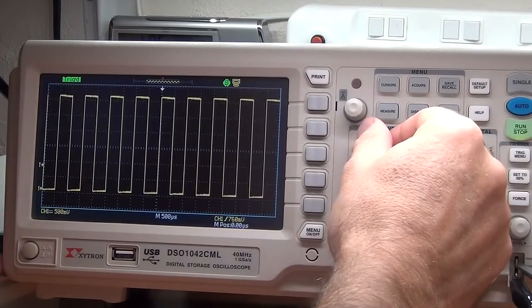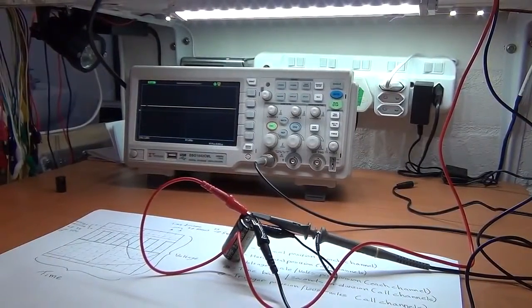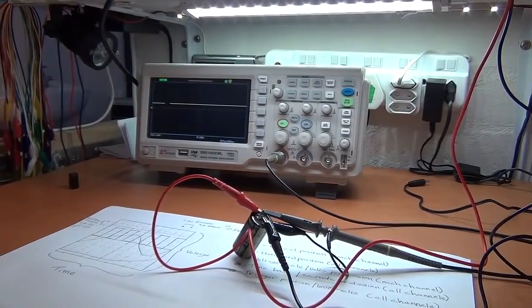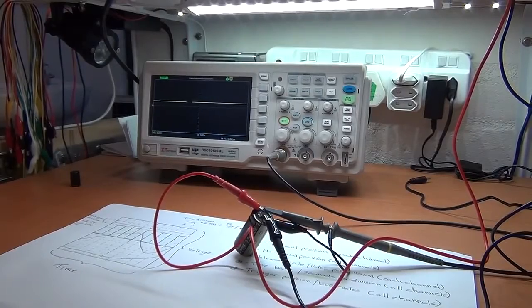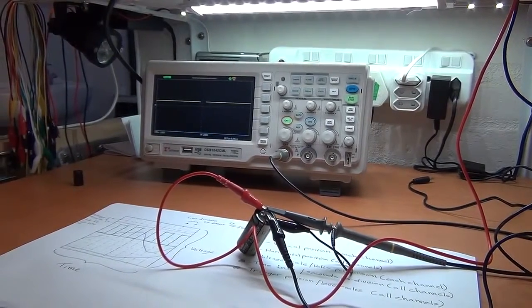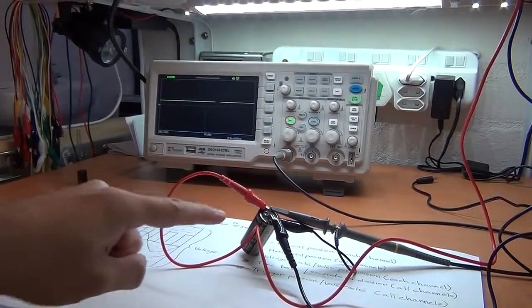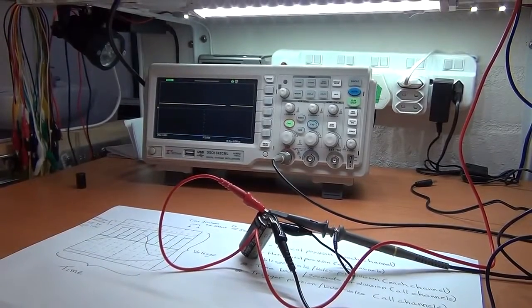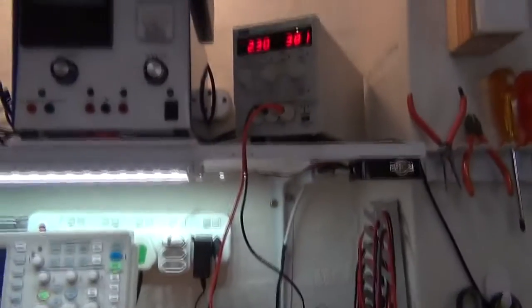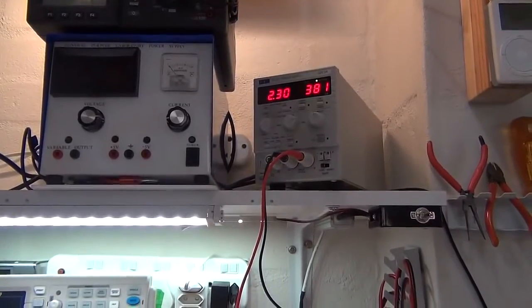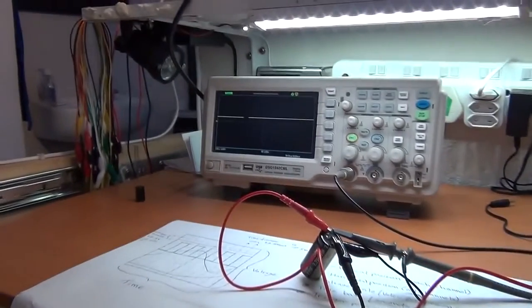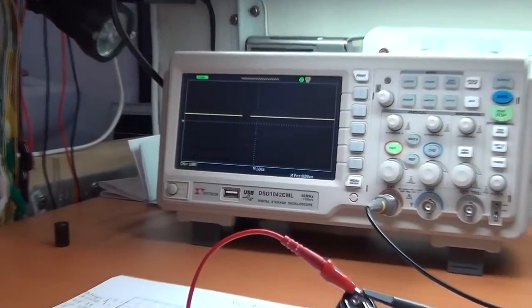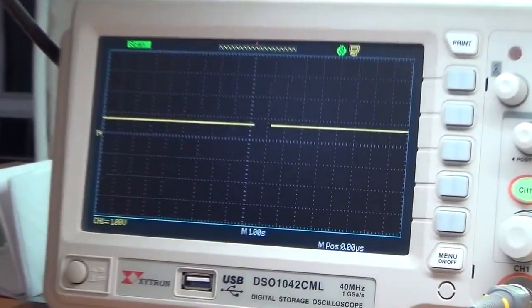Right, so before we end this tutorial, I thought I'd quickly show you again one of my favorite things to use an oscilloscope for, and that's showing a measurement over time of, let's say, something like a hybrid or supercapacitor being charged up. I've got my variable power supply set with a voltage and a current setting, which I'm going to apply to the capacitor, and I want to see over time what that build-up is like.